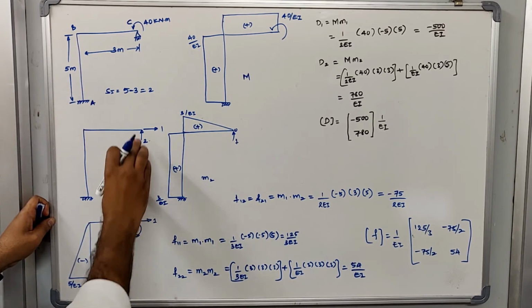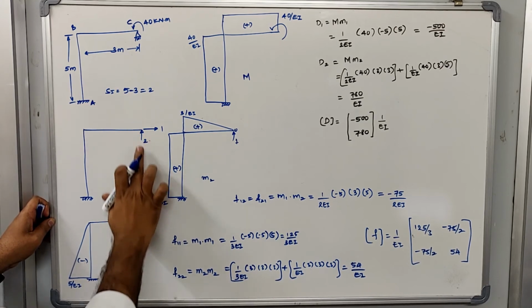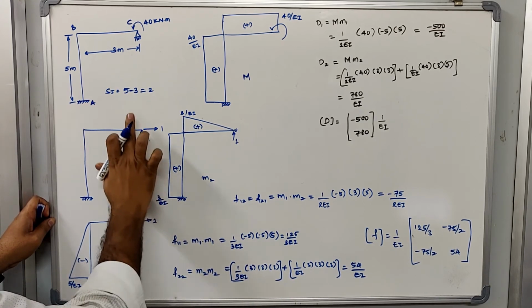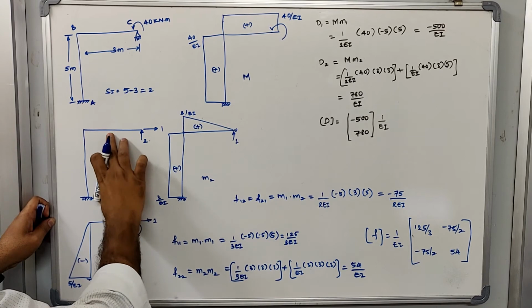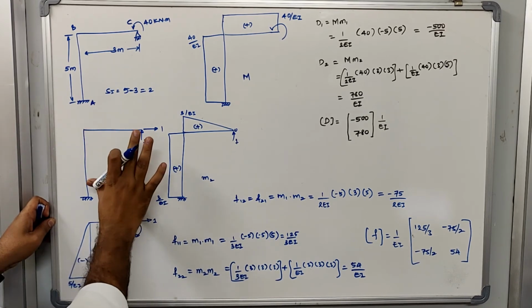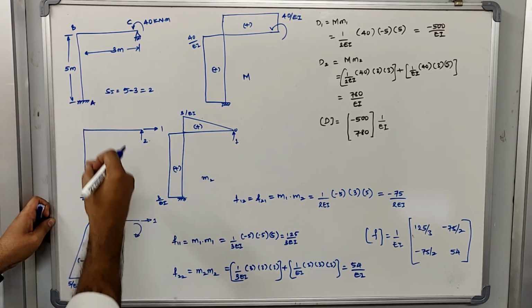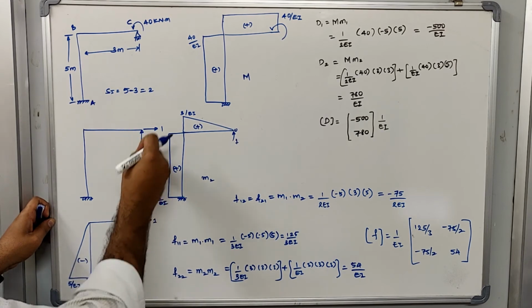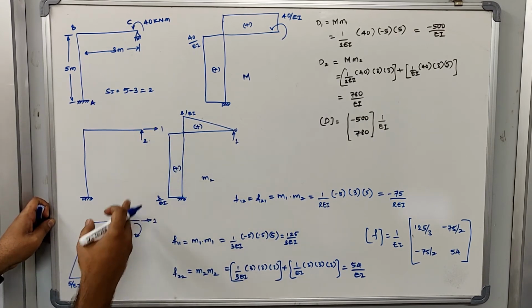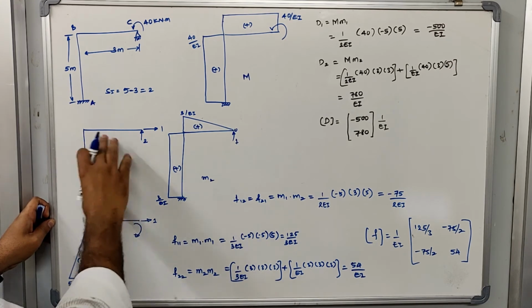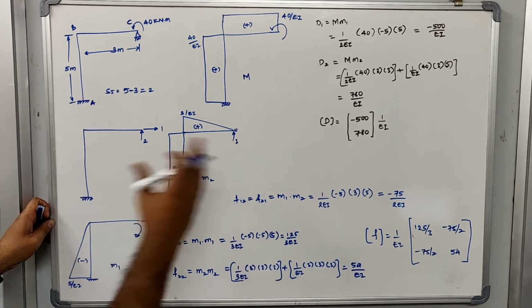Now similarly, if this frame is again subjected to a vertical force in the vertical direction, it is going to translate again. So I would like to see what those translations are by application of unit force in both directions. Whatever translation takes place is our flexibility matrix.